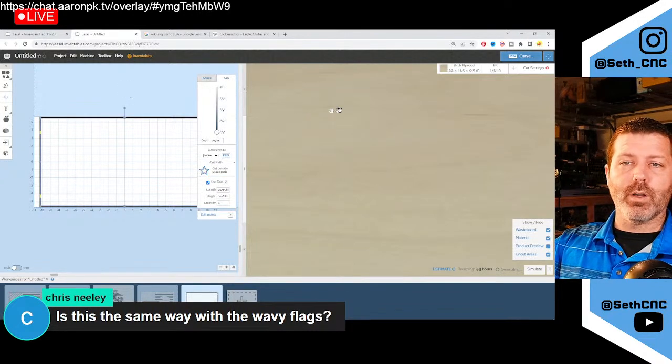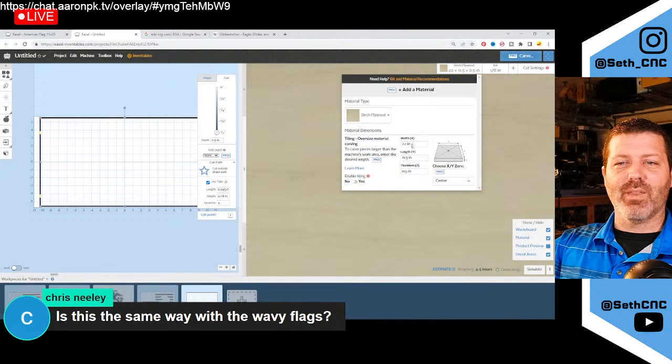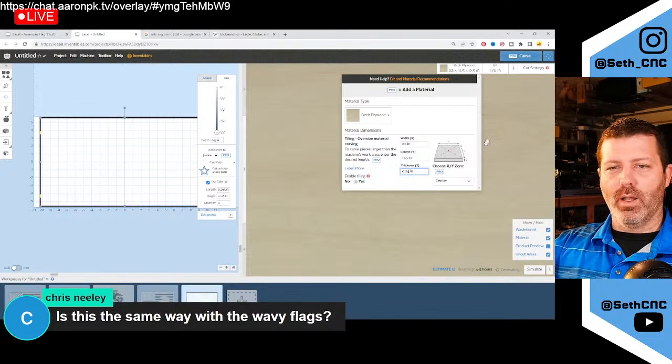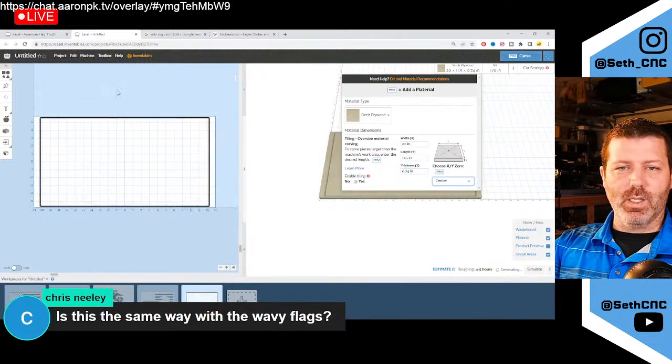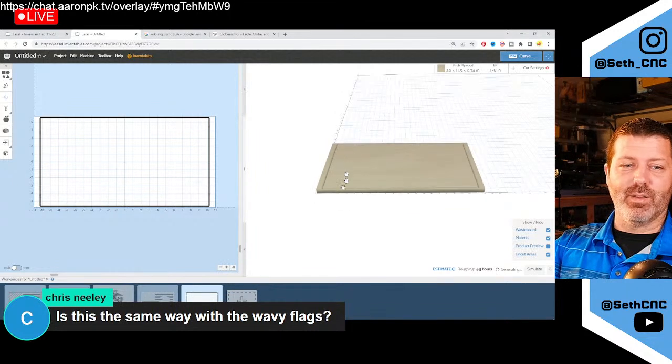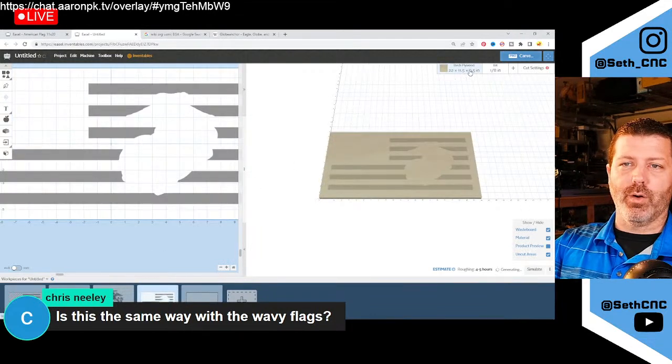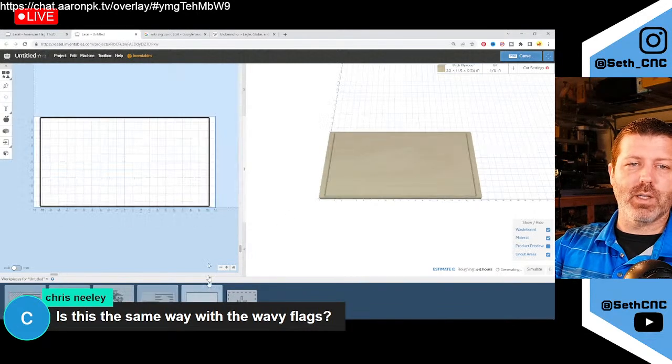And really, this is the one where I didn't do this ahead of time. I changed the length and width of it, but I didn't update the thickness. Usually I use a 3/4 inch 1x board here, so that's actually 0.74 is the thickness. And really, this is the one that needs to have that the most. But if you set that on the first one, it would have copied over when you make the duplicates. But now that I only changed it on this one, it doesn't change it on your other work pieces. Does that make sense, you guys?